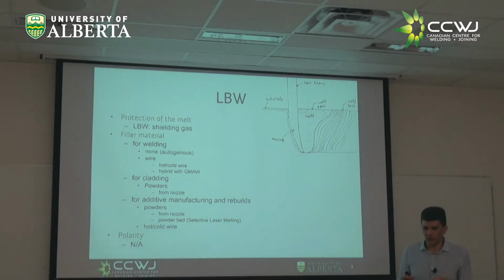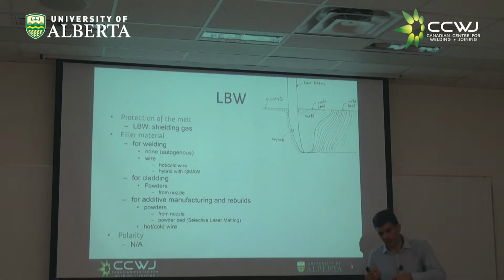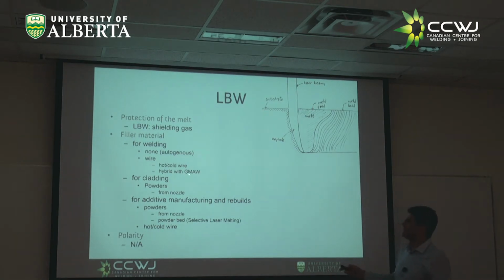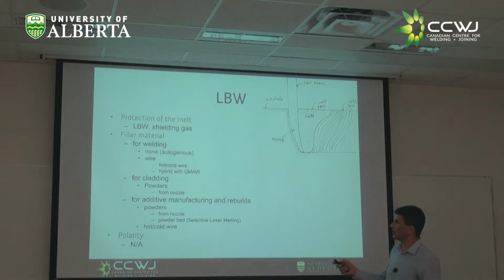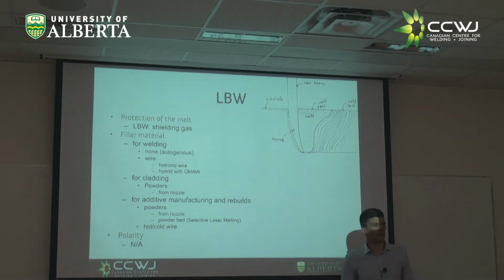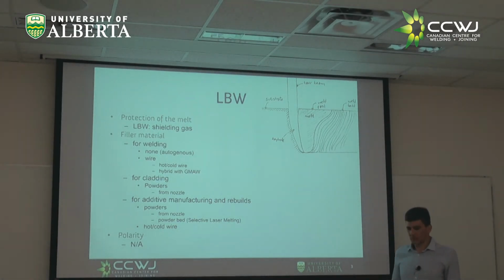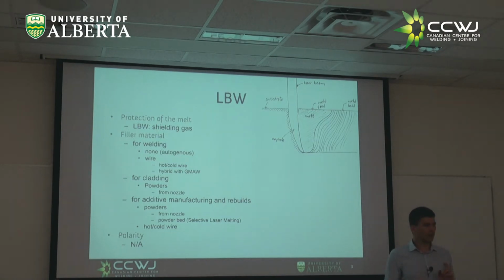And what I do is heat up the weld pool and superheat it enough to melt the wire when it comes in, right? That's very, very hot. So between hot wire and cold wire might look the same, not the same at all. And you can have what is called a hybrid laser arc. In this case, the wire comes because you are putting the wire with a MIG. So you combine the laser with MIG, and I'm going to tell you later some subtleties about that.